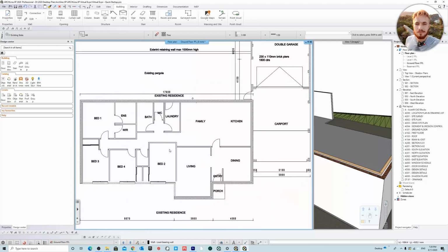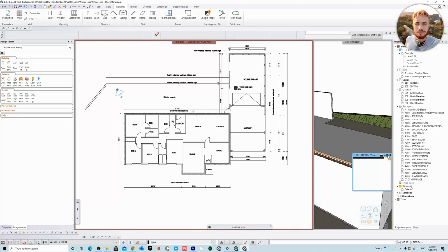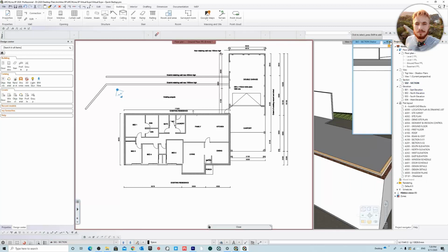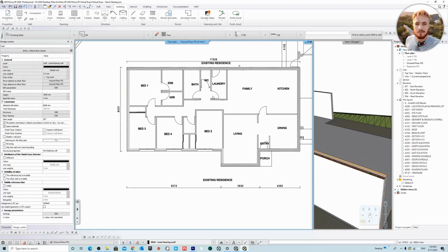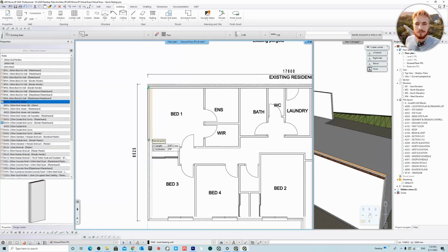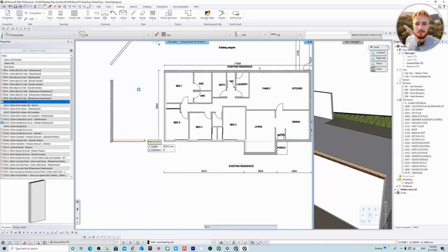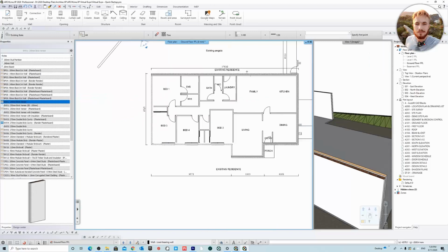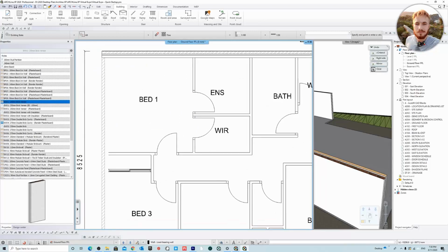Okay, so what we can do is we're just gonna hide our sections. So I'm just gonna hide that section and this one as well so that we don't need this to be refreshed every single time. Now, if we go back and we just go right click, create similar, we can just continue what we were doing before. Okay, so now as you can see, it's going to be a lot faster because we're not constantly updating a section. Okay, so that's if you just turn the sections off, or you can just disable it in the settings. Okay, so let's just continue this.